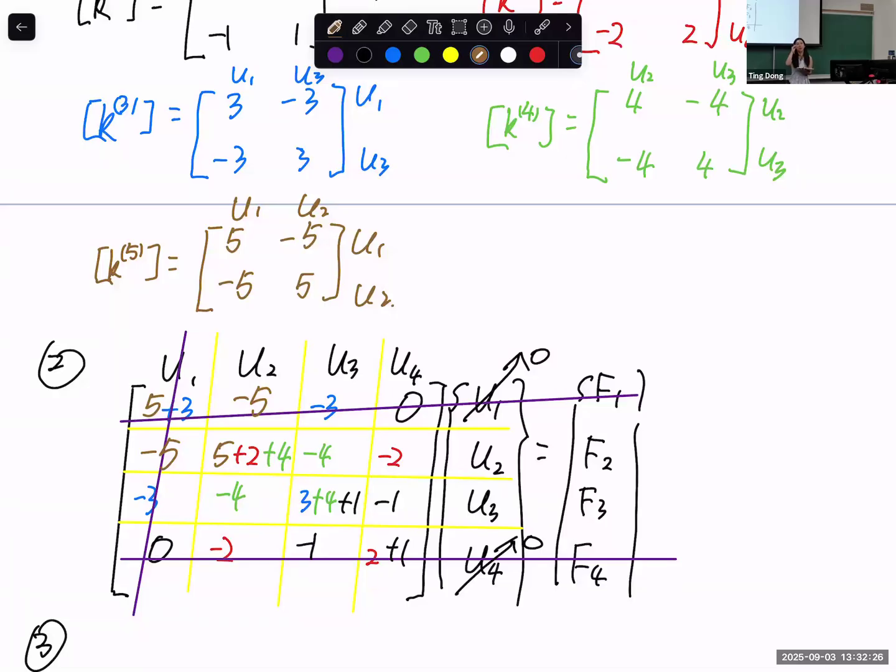Or if you remember some more advanced content in mechanics of materials, internal force is the integration of stress over the cross section, right? So let's say I apply a tensile force, generating tension in this bar element, I cut from here, and the internal force on this cross section is the normal stress integrated over the cross section.